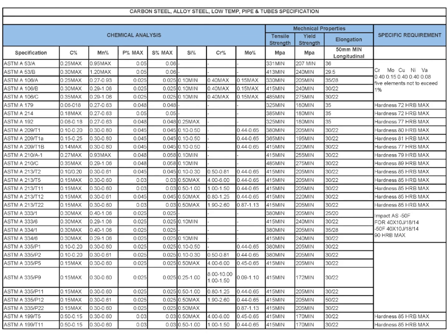These are some examples of carbon steel material: ASTM A53 A, A53 B, A106 A, A106 B, A106 C. These are commonly used carbon steel materials in the piping industry. We have further examples also, and these are used depending upon the conditions of the process.